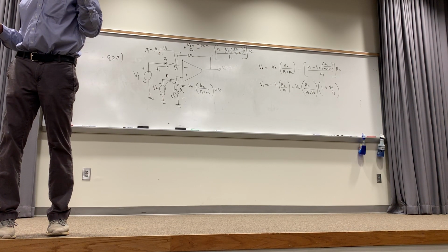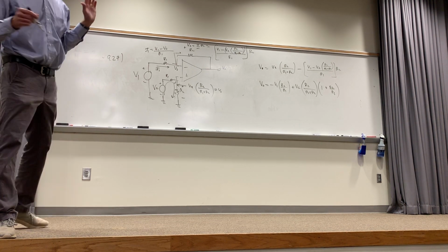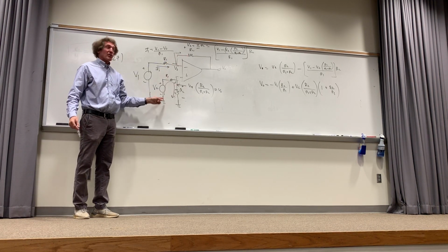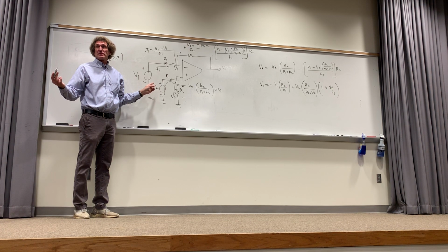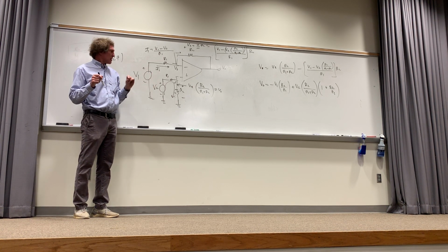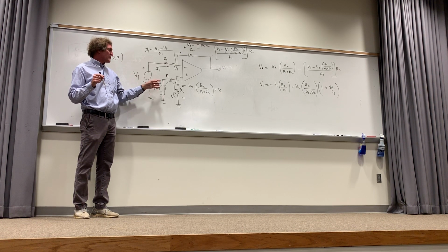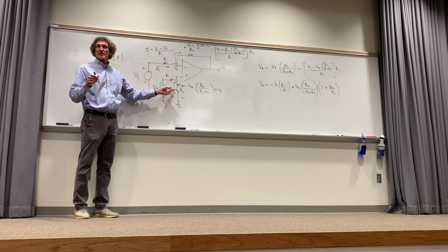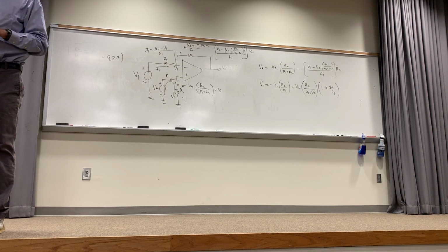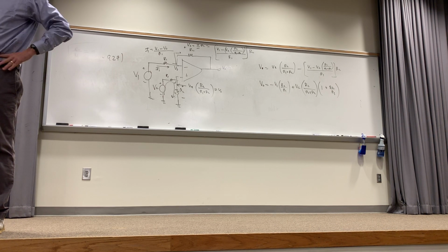Would it also be possible to solve that by solving for current for that loop? When you say that loop, do you mean this loop? No, the bottom loop. Well, once you get that current, you still need the voltage, right? Could you multiply that current by R2? That's what we talked about a little bit ago. Could you also multiply times R1 and V2 minus that resistor? Well, you can take V2 minus R1 times that current to get this, but it doesn't matter how you get that voltage. You need the voltage at the positive terminal for this problem. Got it, everyone?